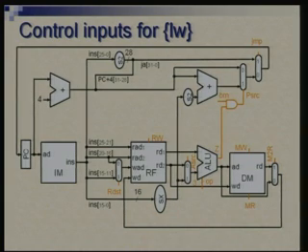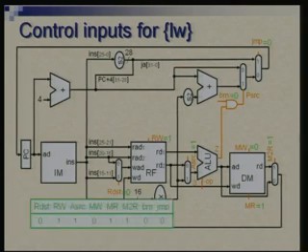Here we are putting things back into register file. So RDST is 0, we are taking the top input. RW is 1, ALU source, this is same as what we had for store, and now we are not writing memory, but we are reading. Okay. So MW is 0, MR is 1, and M2R is also 1, because output of memory is being sent to the register file. BRN and JMP continue to be both zeros. So these signals can be put together again in the table, and this green table which I am forming, I will have to collate these together to form an overall truth table.